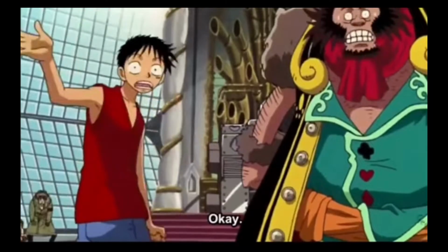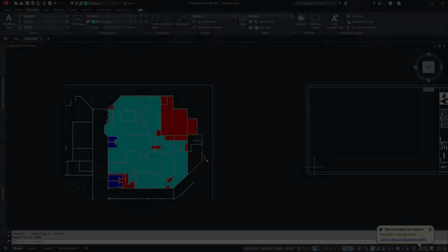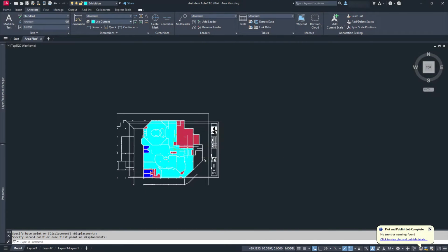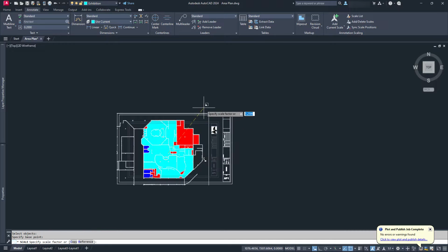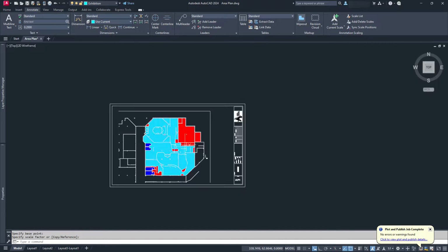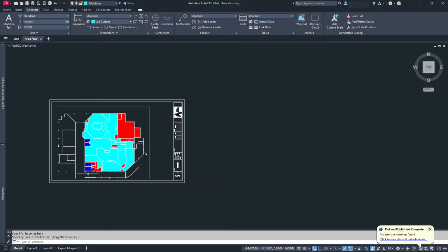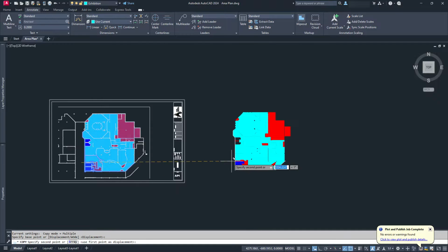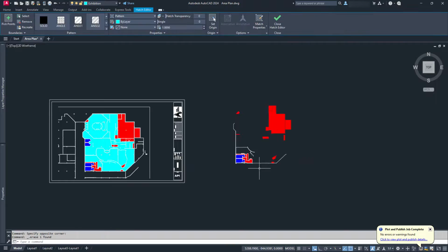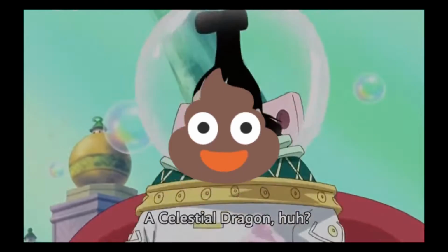Then you have users who configure their sheets in model space, which initially seems easier to do, but can cause a lot of problems. By not separating your presentation from your design, it makes external references difficult, if not impossible. You need to scale their title blocks to fit around the project geometry, making it super hard for users to know what size it's supposed to be printed at. Last, you'll find yourself needing to redraw areas, which means that when a change inevitably occurs, you need to make changes in many places. It's the St. Charles of CAD because it's a piece of...